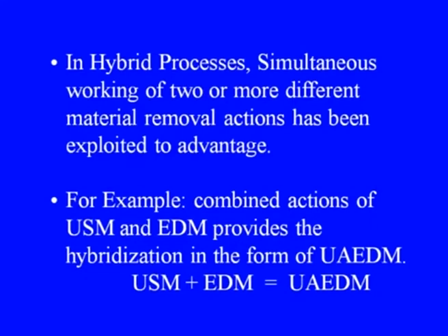For example, combined actions of ultrasonic machining and electric discharge machining provide the hybridization in the form of UAEDM, that is ultrasonic assisted electric discharge machining, in which USM and EDM, both the processes will be working at a time to give the advantage in the form of ultrasonic assisted electric discharge machining.